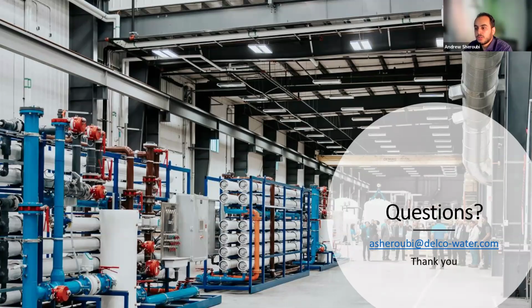The one I like to use most is called a calcite contactor. It's just a vessel. It could be an FRP or steel vessel or whatever, and you fill it with calcite. When you push the water through, the water slowly dissolves some of that calcite, and that adds alkalinity back into the water. One of the challenges with calcite contactors is pH. You do need to have the right pH, and it's a small range of pHs that you need so that it can dissolve properly. That's one method.